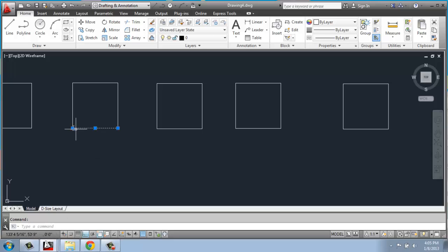If I click on this now, you'll see that, sure enough, it's 4 individual lines now. I can also type in the letter X and hit enter. X is a shortcut for explode. Pick a polyline, hit enter, and now it's burst apart into 4 separate line segments. So in a way, the process of creating something with lines or polylines and then joining them or exploding them is really fairly fluid. Depending what you're looking for, it's fairly simple to go back and forth to get what you're looking for.